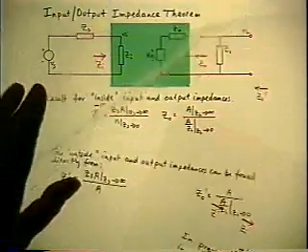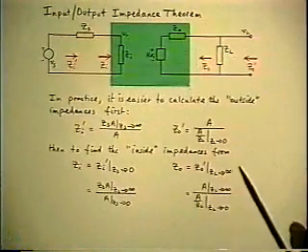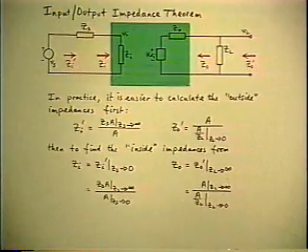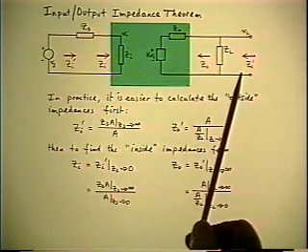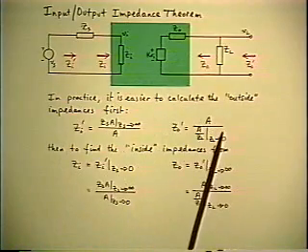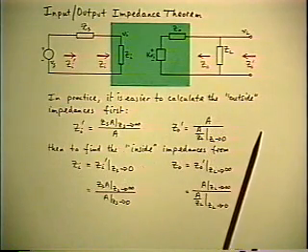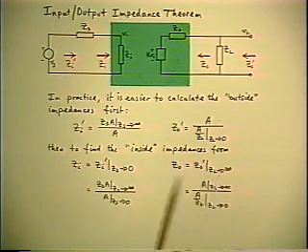Which means that in retrospect, we really ought to reverse the order of those two expressions, because regardless of which impedances you want to find out, it's always easier to calculate the outside ones first, because only one limit's needed. And then you can calculate the other ones by taking the other limit in the answer you've got already.